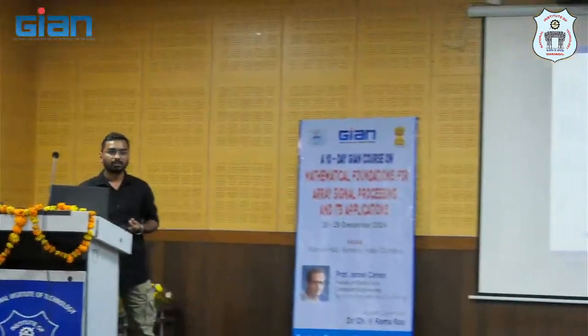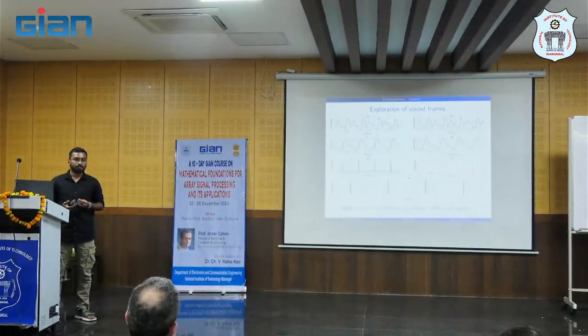This initial testing shows that for one frame, it still gives the peak relatively well even at minus 10 dB SNR. We are still yet to test it on more varied data like many speakers, many languages, or more noisy, more reverberant cases. But this is just simulated, and we're able to estimate the time difference of arrival in this case. So we're still in the exploratory stage.